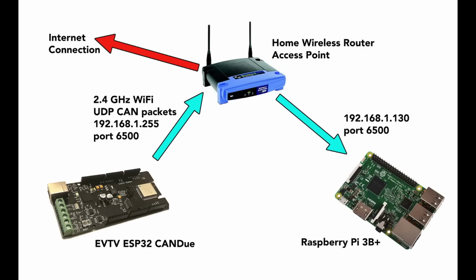And in our ESP32 device, which we now use to control the Tesla battery modules, we send out CAN data on the CAN port for our EVIC display, and to do other things, control chargers and so forth. I can simply add a little routine to every CAN packet that I send out of the CAN port to also send it on port 6500 to the broadcast address on the Wi-Fi access point.